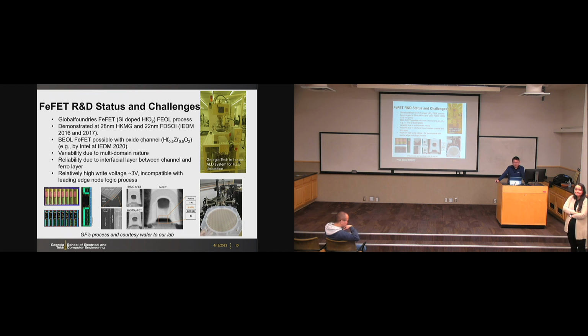So just one last question. For GlobalFoundries, I'd say that the FeFET is better than the MRAM. It depends. MRAM also has good attributes like longer endurance, but of course the challenge for MRAM is that the current write energy is so high. The switching current density is very high, so you pass a lot of current to switch it. So from the write and energy perspective, the FeFET of course will be better because it's field driven instead of current driven. The MRAM is good, I mean, for endurance.